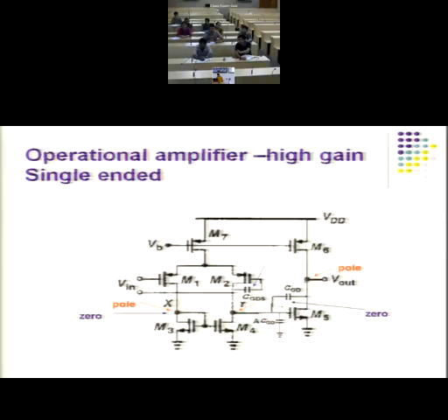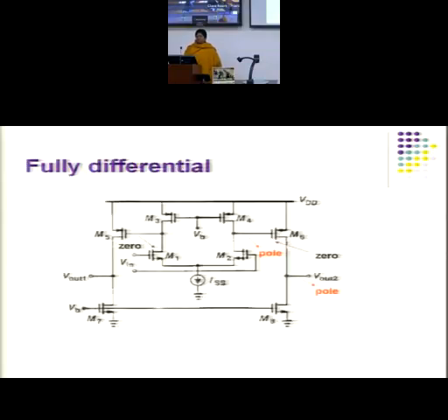Yes, ma'am. So if I show you another structure, identify how many poles and zeros this will have intuitively. It's a fully differential amplifier. So this will give you maybe an input pole and a zero. Output pole will come. Okay, 2 output nodes. A pole will come and then a pole at this, and remember this is a common source amplifier with PMOS input. So you will have a CGD over here. So that will introduce a zero, a feed forward path.